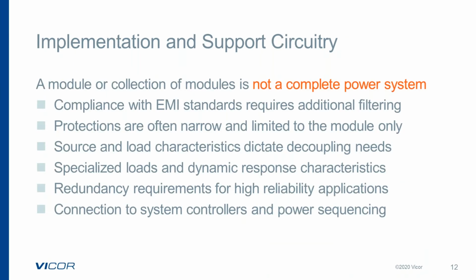Now, once the blocks are configured using the DC-to-DC converter approach, we're not done, because the DC-to-DC converters in many cases do not include EMI support. And in that case, the EMI is needed external to the DC-to-DC converters. We also need to make sure that we have the right amount of protection for the converter in terms of fusing. And this is where all of the support circuitry that's needed for the DC-to-DC system or the power system is defined.